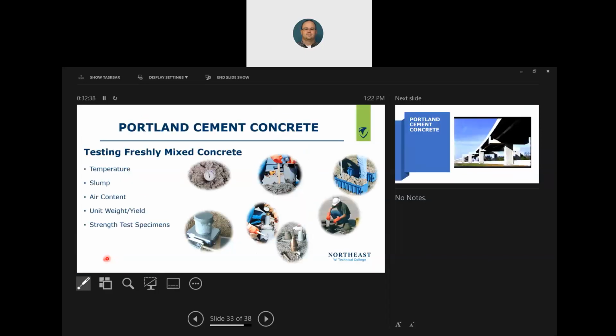All right. Testing freshly mixed concrete. So this is what you are going to be doing, and I'm going to offer you the ACI certification. So typically we're going to measure temperature, slump, air content, unit weight, yield, density, and strength test specimens. Okay.